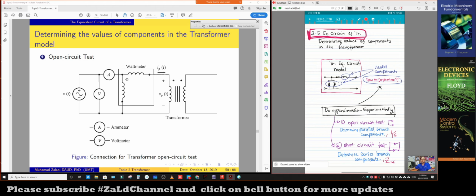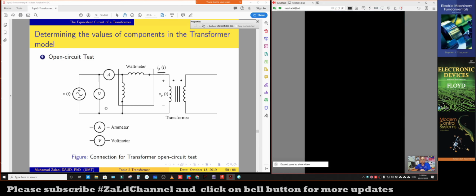Okay, so what we do is measure the values at the primary side. We place a voltmeter to measure the voltage across this supply, VT. Then also the ammeter to measure its current, and the wattmeter to measure its power. Then we will get power at open circuit, POC, current at open circuit, IOC, and voltage at open circuit. Another measurement that we can do based on this setup is to measure the cosine theta, which is the power factor of this transformer.